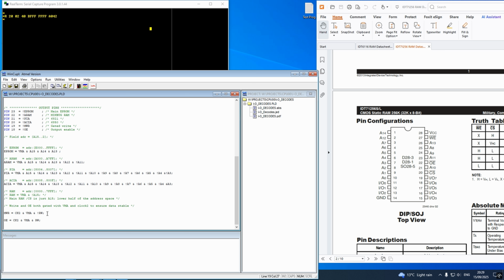So basically that's delaying the write signal until after the data bus and address bus have totally stabilised, because these memories are far, far faster than were available or in this type of size when this system was originally designed in the 70s. And I think it was just a timing glitch, which is what I thought I would try the other mod adding the VMA signal. It's just a timing glitch that was allowing false writes.